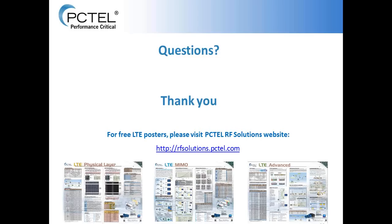It's the electronics behind it, and you have a lot of different types of infrared cameras, all the way from very low-cost ones to very high-cost ones, and some of them may be malfunctioning, or they may not be real strict. They had some tested by the FCC, but later ones they changed the manufacturing process. And they can put out signals that are either harmonics or signals that might interfere with a cellular network. But we've actually found security cameras and infrared cameras that have caused interference in networks.